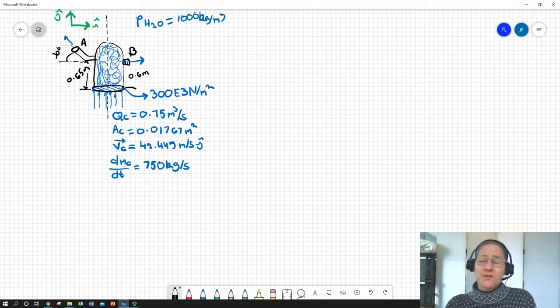You can think of this as a slightly different flavor of the reference volume argument that we use to get our momentum change due to the flowing fluid. We're still going to have a velocity and a mass flow rate, but when we look at the force being applied at a given point, it's easy to say that water's not moving inside this pressure vessel. It is flowing through, but once it's in here, any given water molecule is just kind of moving around. It isn't until it gets right up against the nozzle that it accelerates.